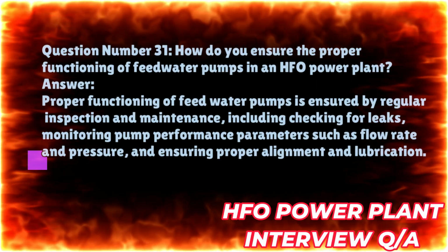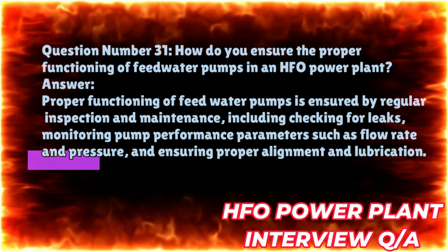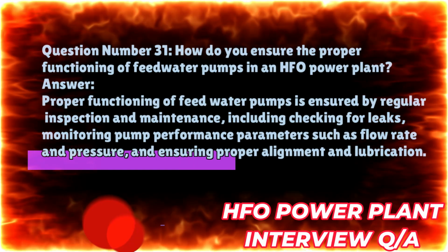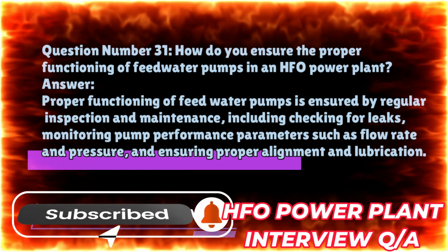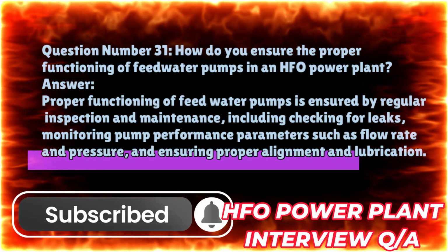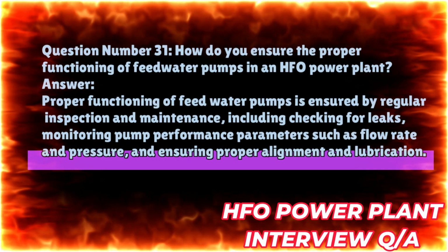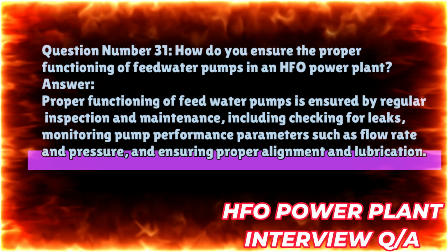Question number 31. How do you ensure the proper functioning of feed water pumps in an HFO power plant? Answer. Proper functioning of feed water pumps is ensured by regular inspection and maintenance, including checking for leaks, monitoring pump performance parameters such as flow rate and pressure, and ensuring proper alignment and lubrication.